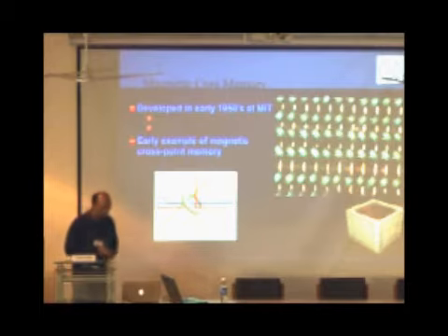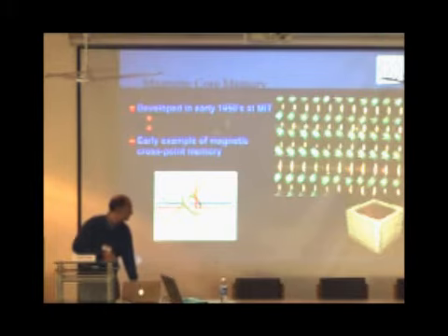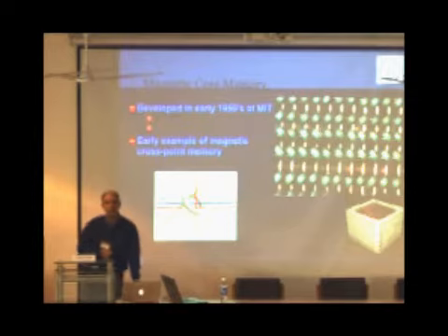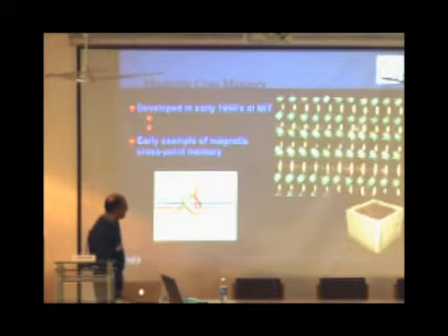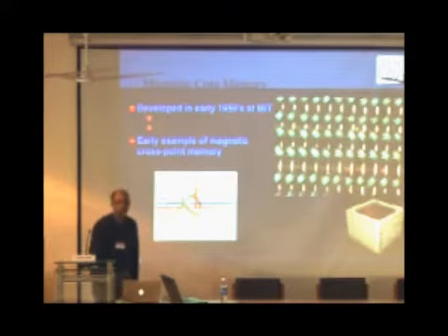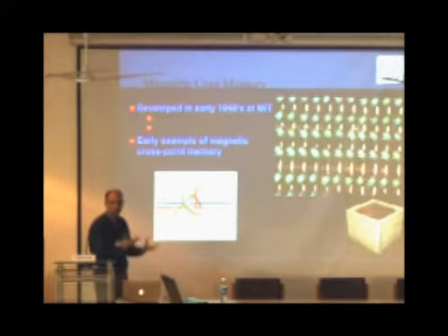What you see on this picture is actually the zoomed in version. Each and every core here is a ferrite core which stores 1 bit of information. However, what is more interesting is that it's actually woven into a fabric. All this fabric that you see here are interconnects for winding the cores together to form one single big block of memory.